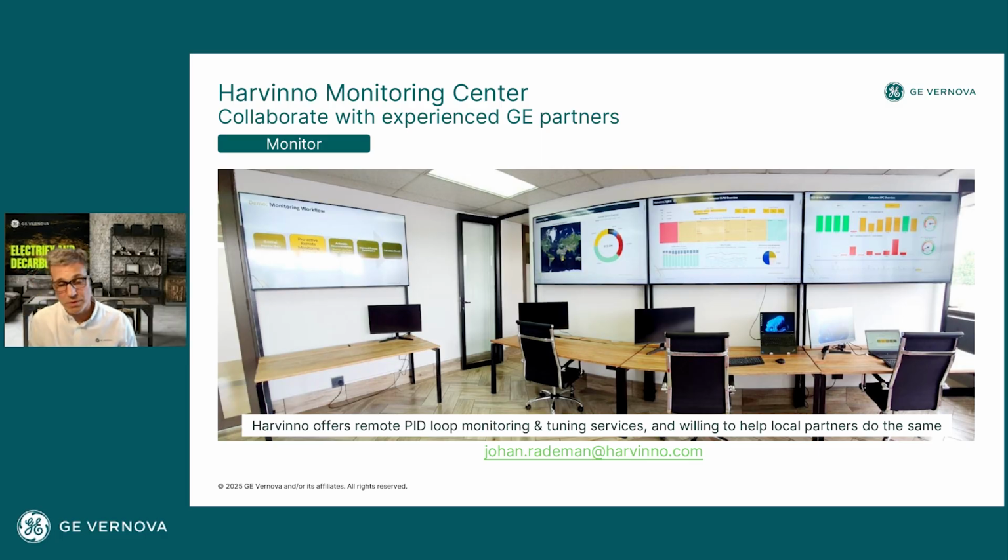And so it typically will be that they would have weekly calls with all the different plants, discussing what they are seeing, and how the processes are performing and how all the PID loops are performing. They're providing tuning services for the PID control loops remotely. And then also, if they identify bottleneck areas in the plant, they may help these customers implement advanced control or optimization analytics to maximize production through those bottleneck areas.